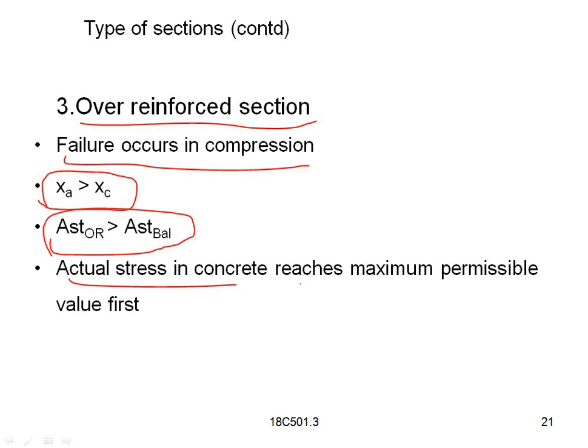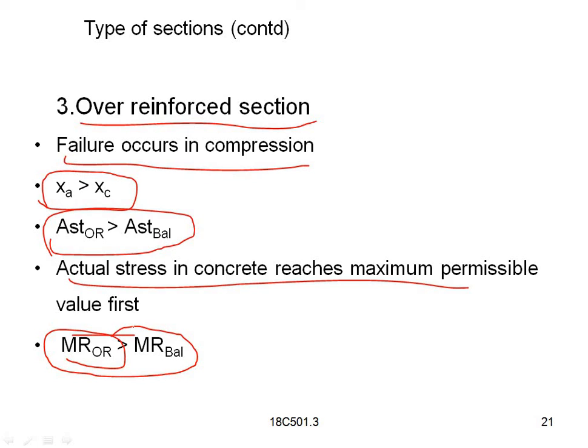Actual stress in concrete reaches its maximum permissible value first. So the moment of resistance of over reinforced section is greater than the moment of resistance of balanced section.